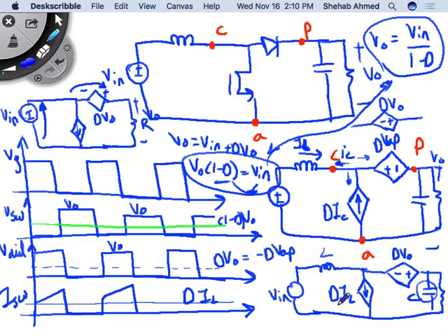Fine, you have a Toyota, and then the other guy has a Lamborghini. It's independent of the driver, right? So you put the worst driver in the Lamborghini, that's the controller. Put the best driver in the Corolla. There's still a physical system limitation. Here, in power converters, it's the L and C size. That's the limitation. Small L and small C, very dynamic. You can change things very quickly, charge, discharge quickly, do stuff quickly, like a Lamborghini. So, good analogy.